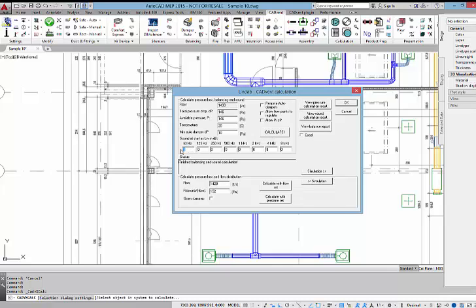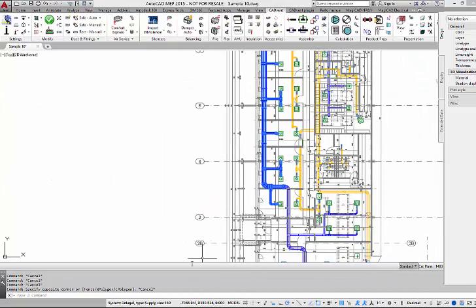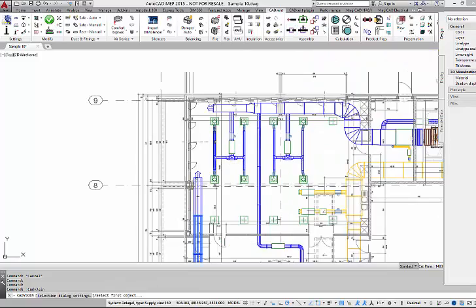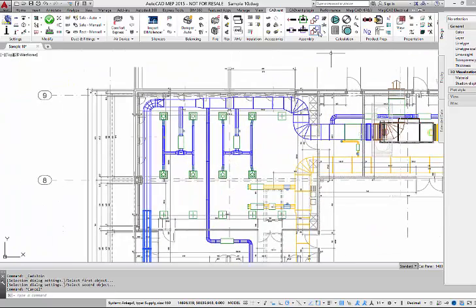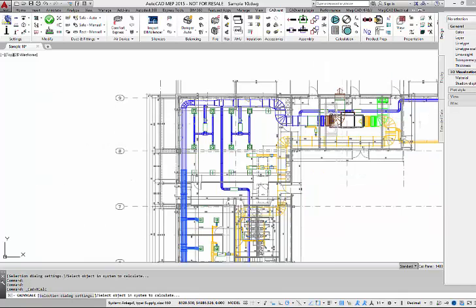If you have a sound at the start of the system, we can also make a complete sound calculation. To do so, I will connect the systems here now. Please connect the ducts with the rectangular duct here. And we see here we have an air handling unit already, and this handling unit has already predefined sound value. So let's do the system calculation here for the complete system.